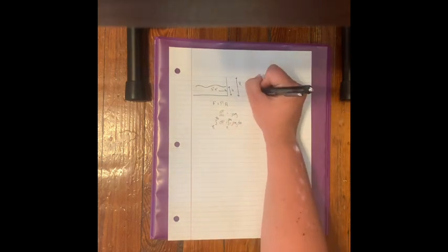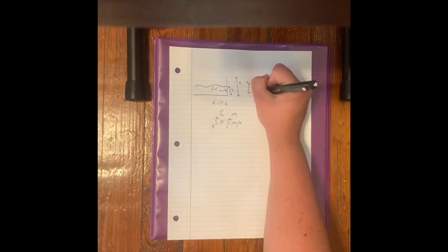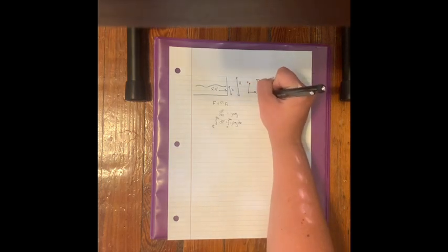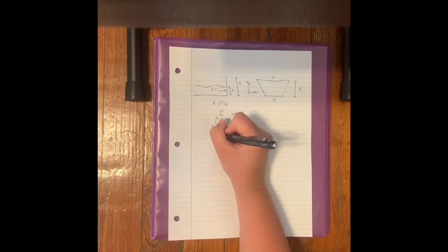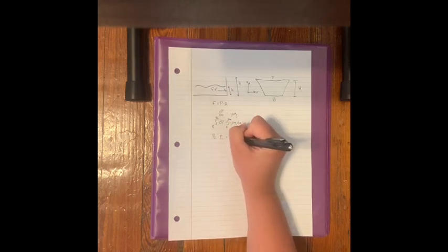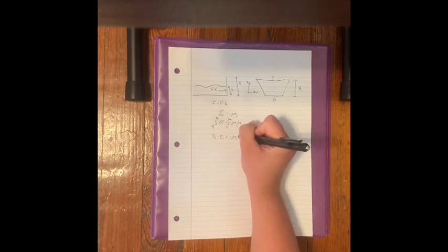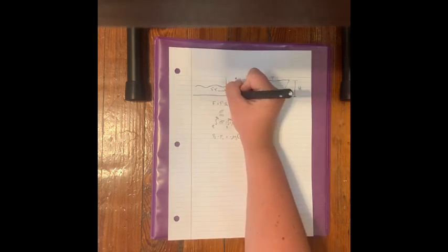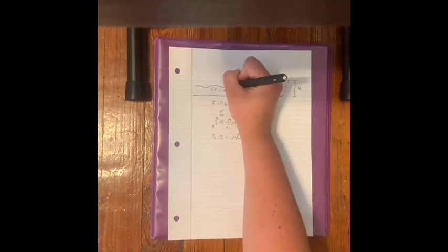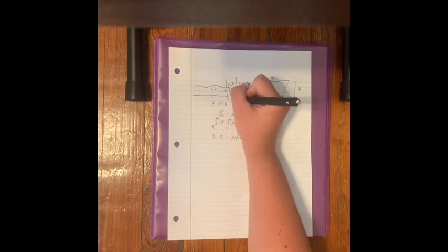We're going to define the upward direction as Z, and this way will be positive X. When we integrate this, we get P2 minus P1 is equal to the negative density times acceleration due to gravity times the quantity of Z2 minus Z1, where this location is Z1, this location is Z2, there's some pressure here, and the pressure here we're going to say is equal to 0.